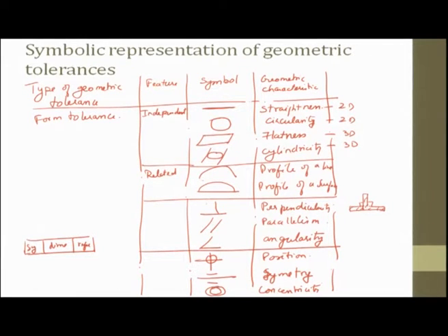All these symbols are available ready made in several of the handbooks. So, what you have to understand is looking at these symbols. Why are these symbols important? Because you are talking about geometric tolerance. Geometric tolerance is important because till now what we were talking about is only dimensions, but geometry also plays a role. For example, if I take a shaft and measure the diameter of the shaft, at every section plane, it will fall under the dimensions, whatever it is.